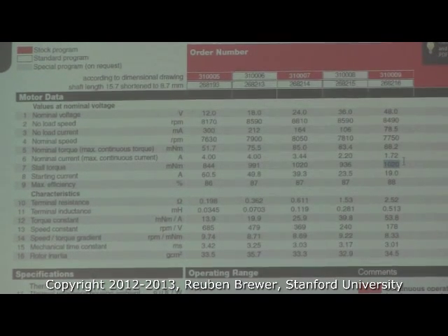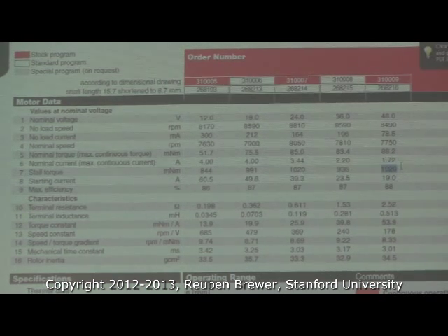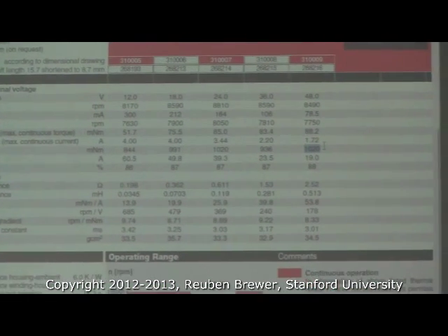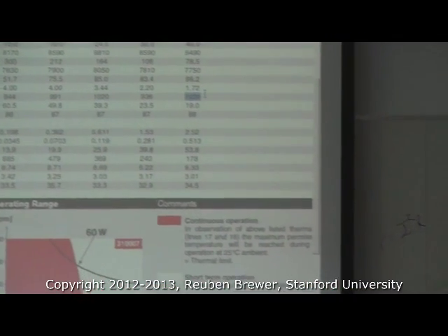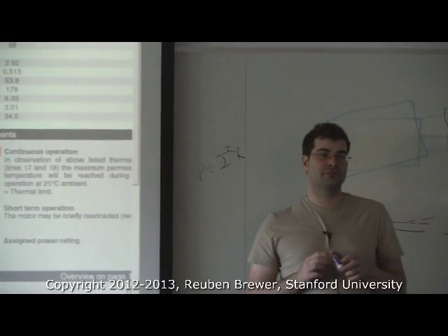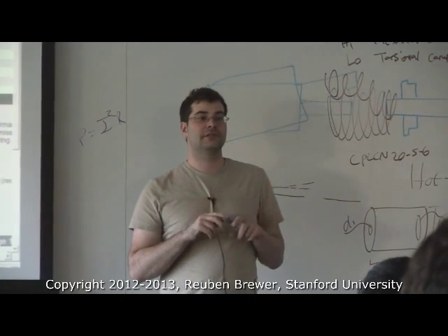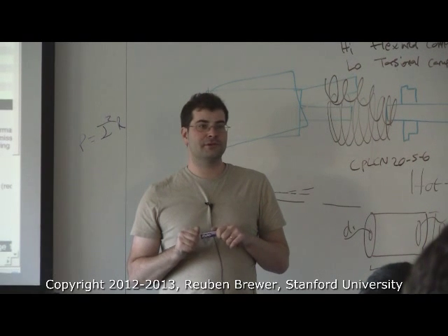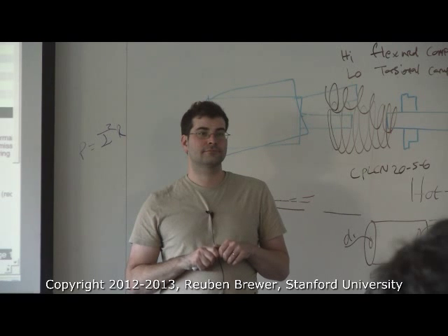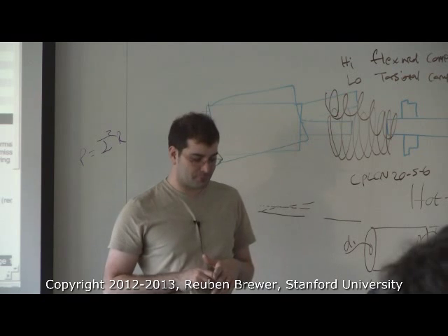Yeah? Doesn't the motor cool down faster if you let it spin fast and it has that little fin in the back? Rather than stopping the motor and then restarting it. You're talking about drill motors that have little fans, and Maxon motors don't have little fans. So yes, you're right, this one has little fans too. That's a really cheap Chinese-made motor, literally taken from a drill. Normally motors don't have little fans in them. They spin and then you have a gearbox that connects and disconnects, so your motor is always spinning, but you either connect or disconnect. Not the case for the precision robotics that we're doing.